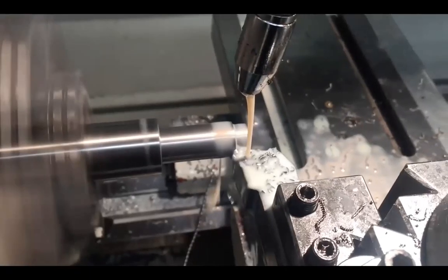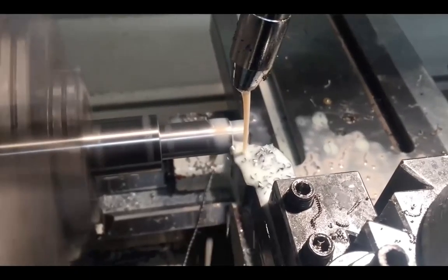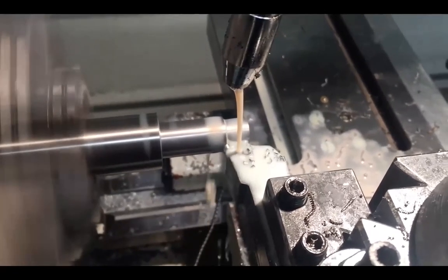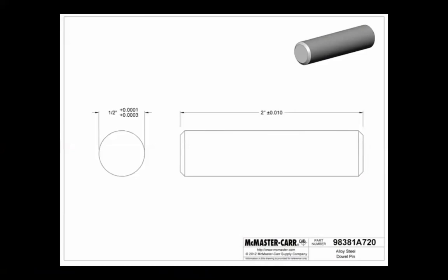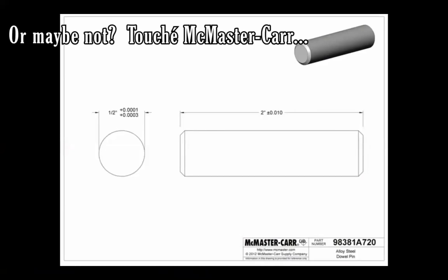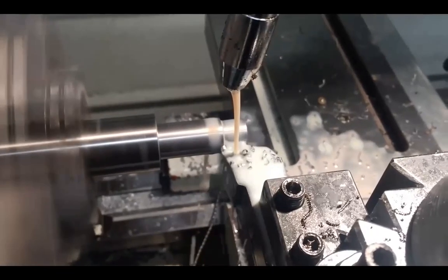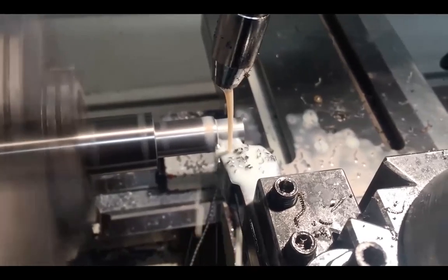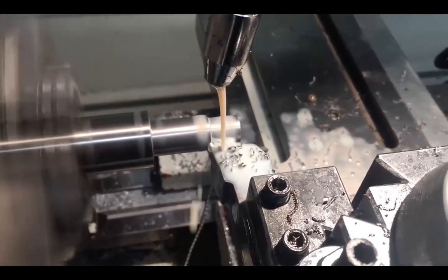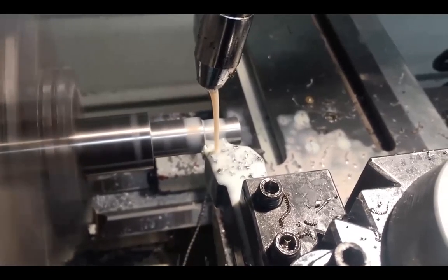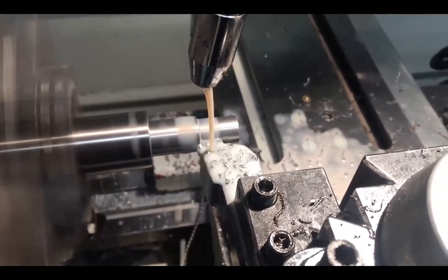Conveying tolerance zones can be a bit annoying. Say you own a factory that makes dowel pins. You want to be able to tell customers what the tolerance zone is on each size of dowel pin, but it would be cumbersome to have to create engineering drawings for each size. So instead, you can just say the tolerance will always be a bit over the specified dimension, where a bit over scales roughly proportionally to the target size. We could say that all the pins will be between 0.1 and 0.3% larger than the nominal dimension. The problem is we don't want people to have to constantly calculate what these percentages are.